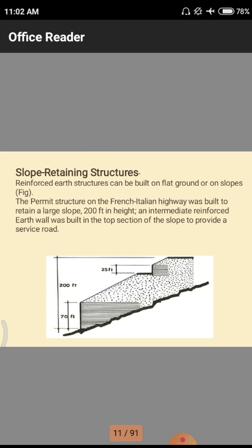In those areas we construct this reinforcing structure or slope retaining structure, so that the bars have a tendency to pick up all those materials, and that will control the further erosion process. That means further on there may be no erosion due to this reinforcement. Okay, this is the best example we have to observe in this diagram and cross section also.